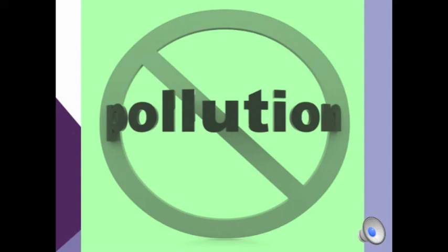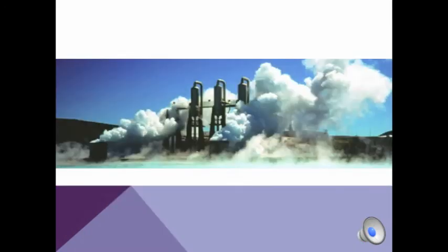Another such gas that can sometimes be released is hydrogen sulfide. Hydrogen sulfide is a serious health hazard to people, so to prevent this, geothermal energy plants have scrubber systems to clean the air of hydrogen sulfide. Geothermal fluids also contain higher levels of arsenic, lithium, boron, and mercury, and if this waste is not disposed of properly, then it can be a serious problem to wildlife in nearby aquatic areas. So this water is generally put back into tanks for reuse. And the steam you see rising from geothermal energy plants is generally just steam.